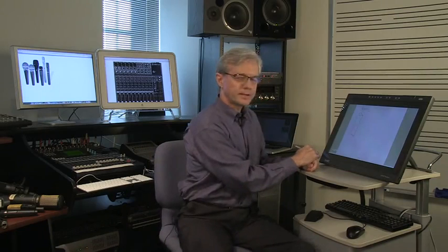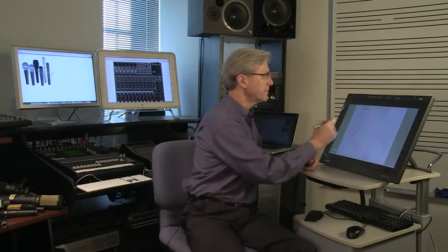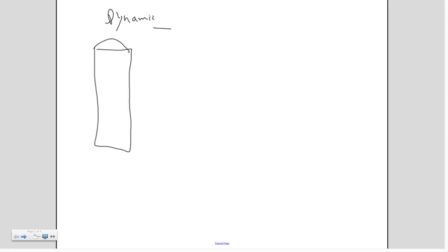There are many different design microphones, but I want to focus on two primarily today. The first one is a dynamic microphone. And this is perhaps the most common microphone that you will discover. The dynamic microphone works under this principle. If we see a dynamic microphone, we will see a membrane covering the top of the microphone. Usually this is going to be polyvinyl chloride or some other kind of thin material. This membrane, or this diaphragm, will move according to the air pressure, the sound pressure waves that hit it. We'll start to move that diaphragm.